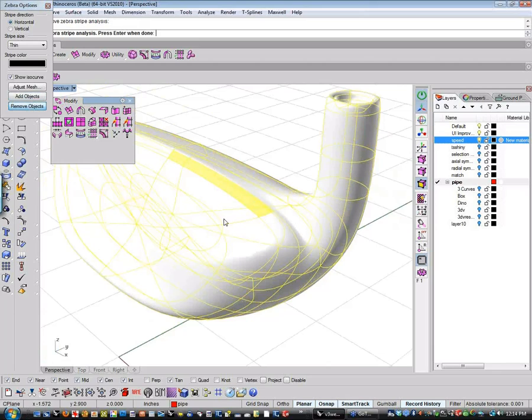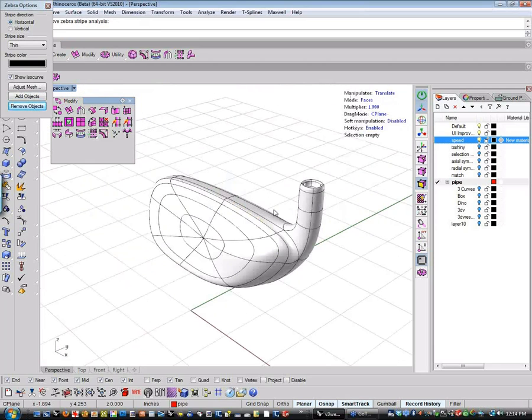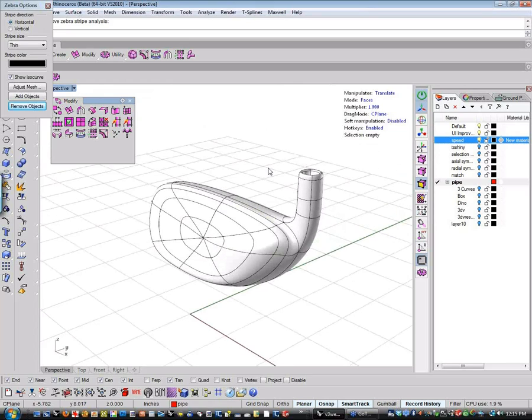So before you do your conversion to NURB, before you do anything like that, you would want to go into compatible mode, then do your conversion. You're going to get the full smoothing and the full effect of all of the T-Splines goodness.